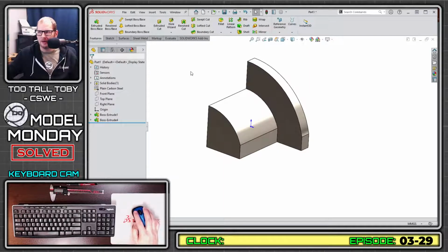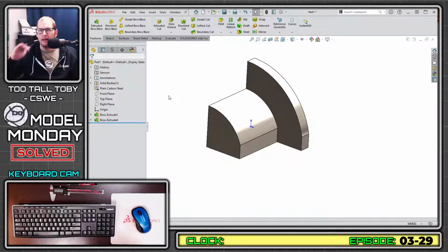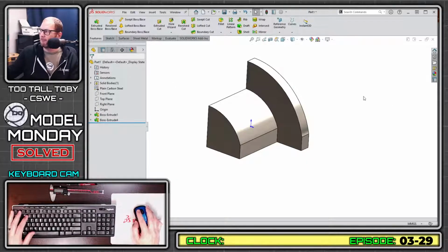So I know from experience to move it a little bit, then right mouse button, and then I know that as soon as I choose reverse direction, the very next move is going to be to right mouse button again. So it's going to be left mouse button, right mouse button, really quick. So now I finally have enough information that I can create that geometry on the top of the model.